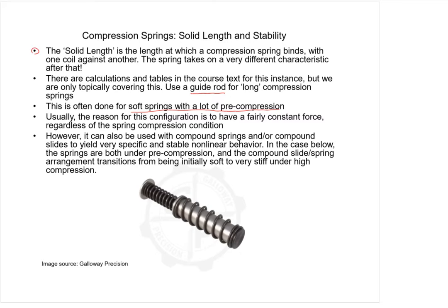So if you take a really soft spring and pre-compress it, and then just work it a little bit around that pre-compressed state, it can become virtually a constant force mechanism, which is kind of neat. You can also use this arrangement with compound springs. Here's one shown below.